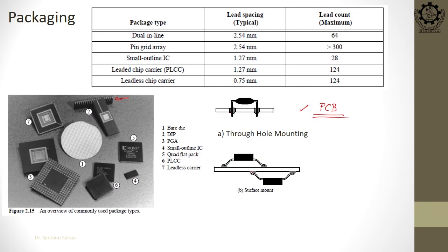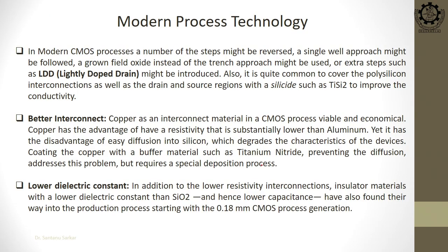And for modern devices, we can have surface mount devices, known as SMD devices. Surface mount devices generally have quite high packing density. Through hole is limited by the area of the hole, and SMDs are very small. So, an SMD capacitor or SMD resistor takes very small area compared to the ceramic resistor or capacitor. We can just solder them directly on the board.